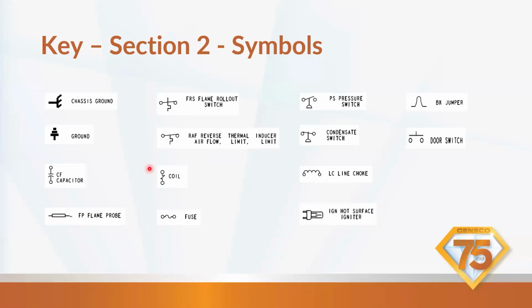Sometimes you're going to see this weird symbol. Looks like a lightning bolt. So what that is a reference to, depending on the model furnace, would be a coil of some type. A coil would be a gas valve coil, a relay coil, anything that's going to be like a contactor coil, right? Technically speaking, it's going to have this little lightning bolt in there, and you're showing that this is not a motor, but this is something that's doing some work. This is closing a contact usually.